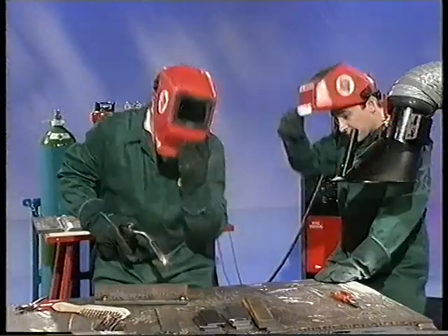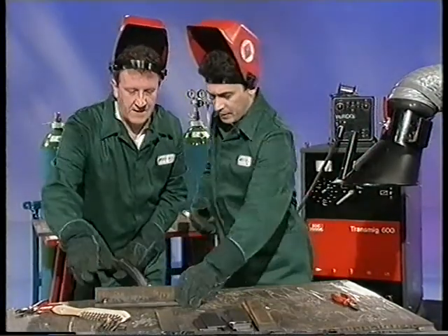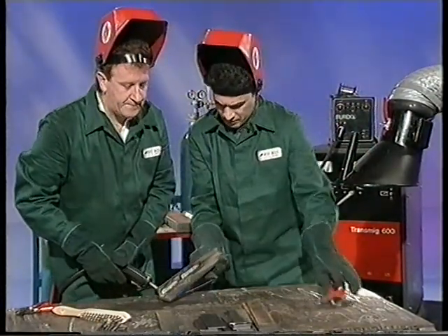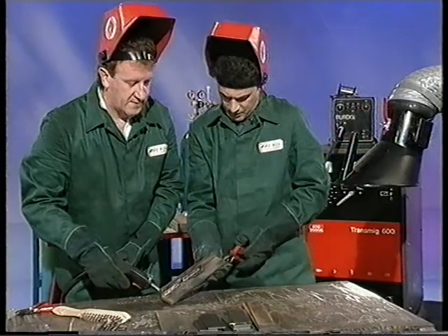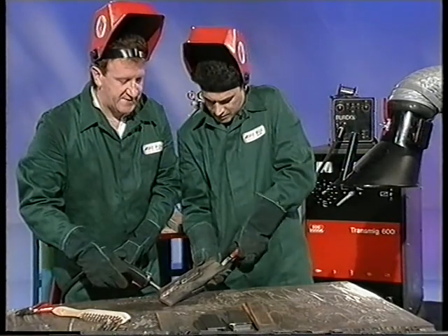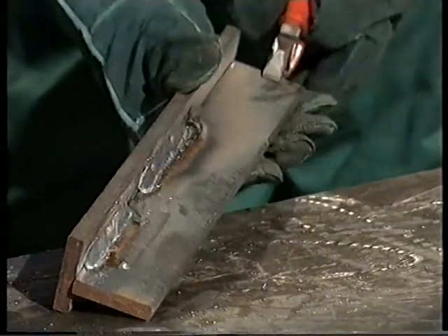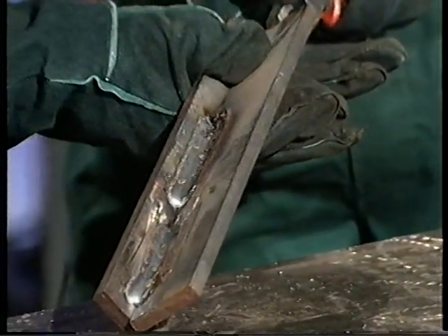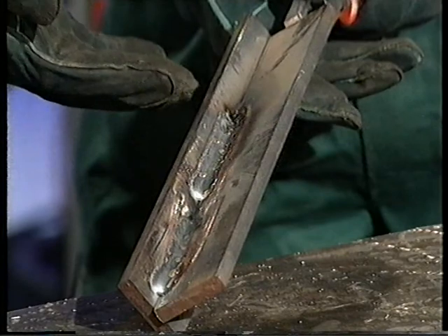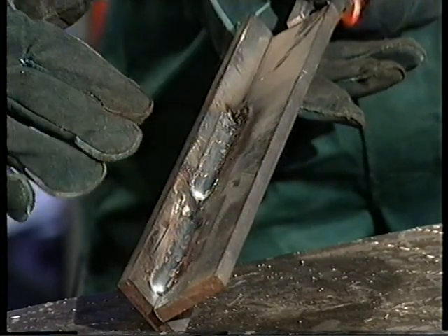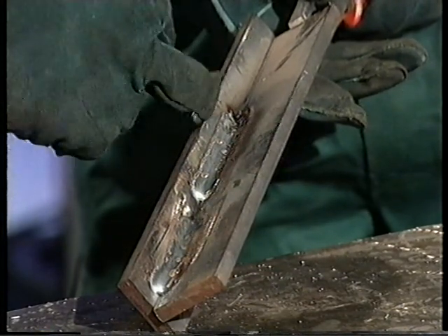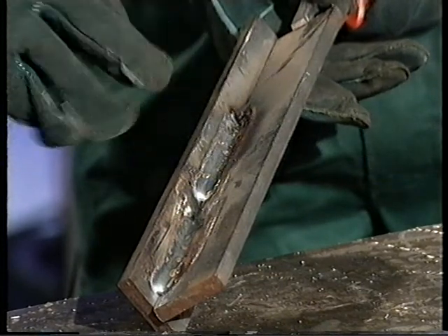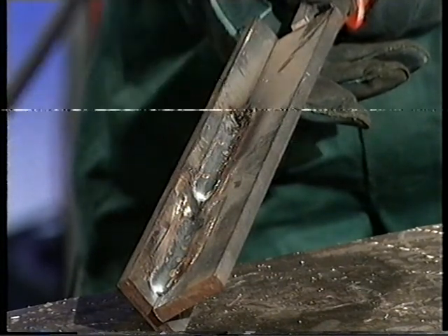A lot of smoke that's being taken away by the extractor. Now, hold that with gloves and the pliers. That's it, got the pliers on, that material is hot. If you could just turn it this way a little so I can see. There we've got reasonable travel speed, reasonably well-defined weld. Maybe, again, I'm being critical of myself, I put too much on the bottom plate compared to the top. It really wants to be evenly spread on both sides of the plate.